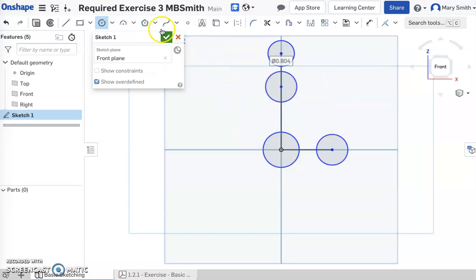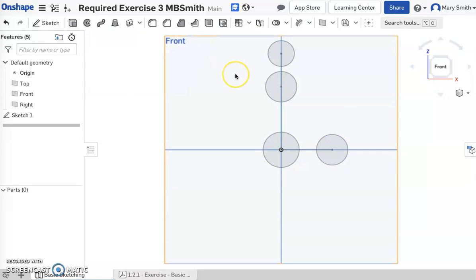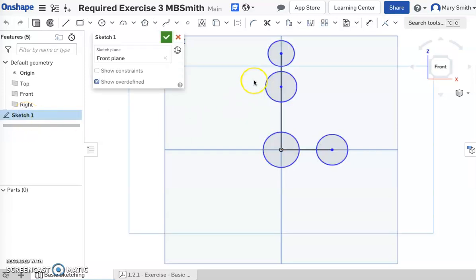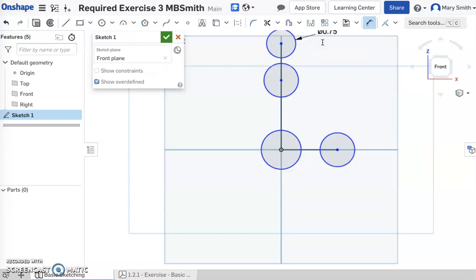All right. I'm going to press the check mark on my sketch just because I know that that's going to save the work I've done so far and move on to the next step, which tells me to define some dimensions. I will have to go back into the sketch, and then all these tools that I need will show up because these tools are for sketching. All right, so some dimensions I've been tasked to assign. I grab the dimension tool. If you click a circle while you're in dimension, it's going to say, what do you want the radius to be? Because that's the typical dimension assigned for a circle.